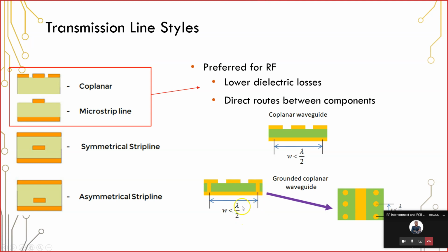But eventually, the signal frequency gets so high and the wavelength gets so small that you can no longer do this reliably. And the reason for that is, number one, manufacturing considerations. I can't keep making this grounded coplanar waveguide smaller and smaller as my frequency gets larger and larger. So there are other things that I have to do to ensure that I can allow signal propagation at my desired frequency. And I'll show you exactly what I mean later when we look at grounded coplanar waveguide design.